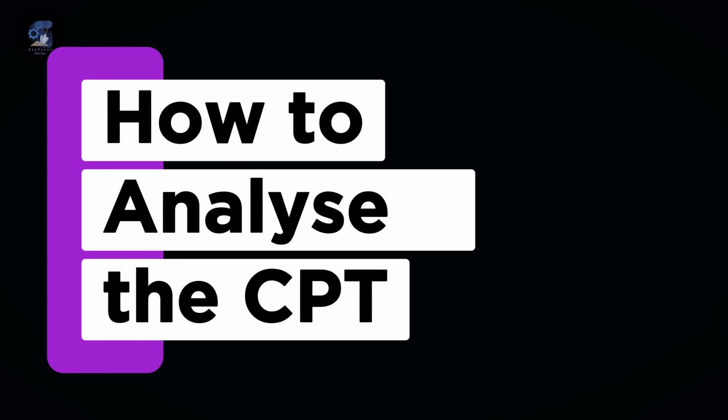So, up to this point, we have seen the cone penetrometer mechanism, but how do we determine, let's say, the type of soil or the strength properties from the tip resistance, sleeve friction, and pore water pressure? You see, over time, numerous semi-empirical correlations have been developed to estimate geotechnical parameters from the CPT for a wide range of soils across the continents.